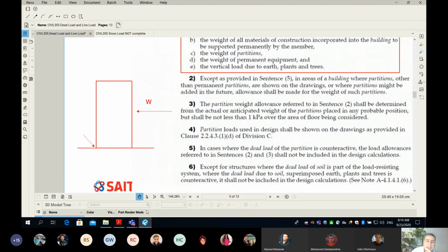Yes, let's stop at this point. You guys are trying to say something, but I think the closest is Martin. Martin is saying the weight of the building. I'm going to show you here an arrow. This arrow represents the weight of the building, and you can see around this point, the wind is trying to make a moment around this point, and the weight of the building is counteracting the action of the wind.